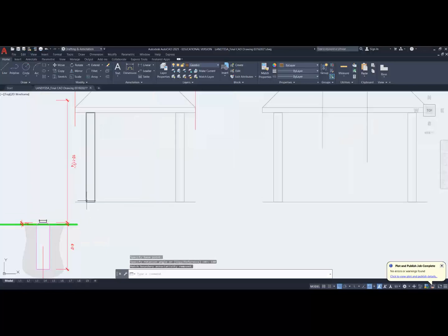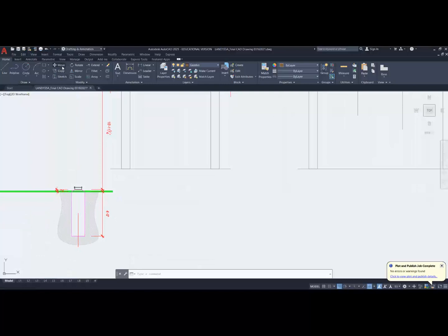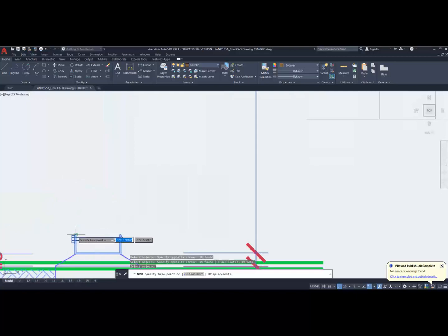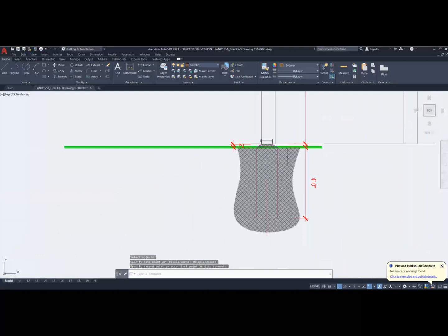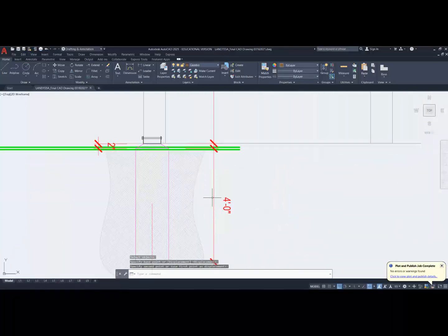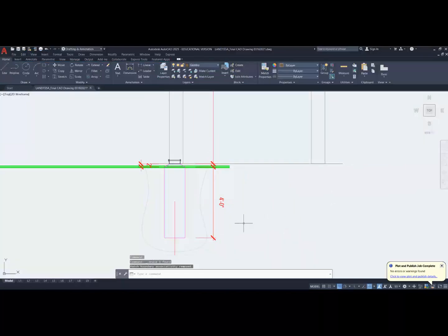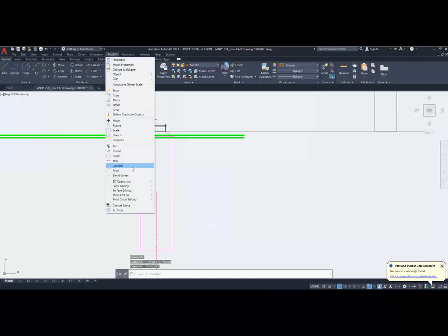And it rotates 180 degrees. And if this is my paver construction and this is my post construction, I'm going to move one to the other. And I can tell right away that this post is actually too small. Or sorry, the saddle that I have here is too small. And therefore, this detail won't work. I'm going to have to modify it, edit it, copy it, change some of the configuration of it. That's okay. Let's get rid of that. Get rid of this. And I'm just going to use the stretch command.